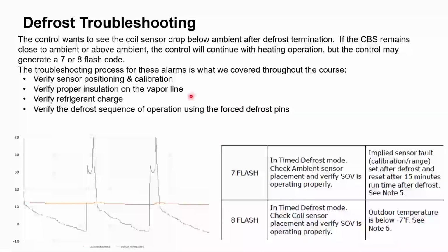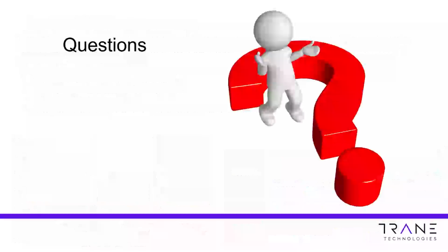Verify charge. Usually this is solved by one of these 3, okay? And then also make sure to verify your refrigerant charge and superheat on your outdoor expansion valve. And then of course, verify your defrost operation. Make sure we're not freezing up oddly.